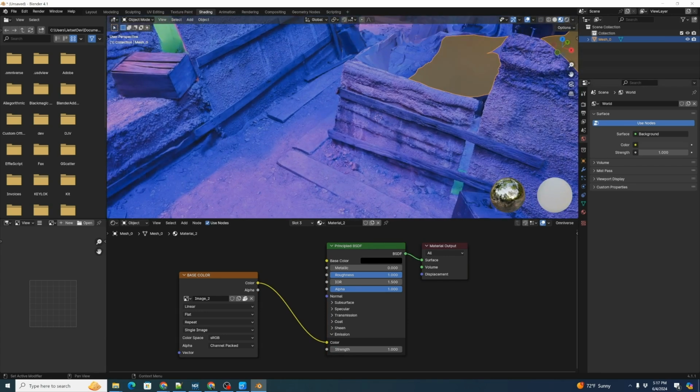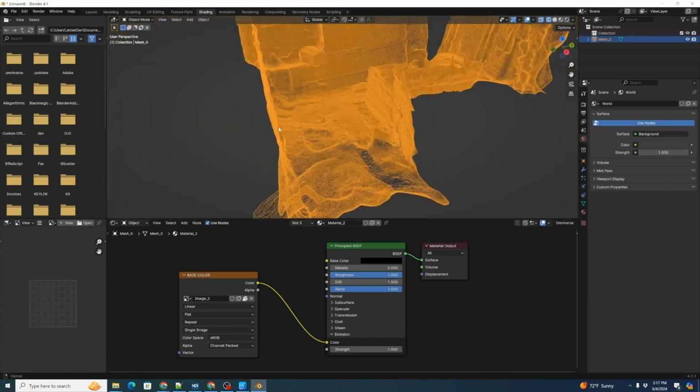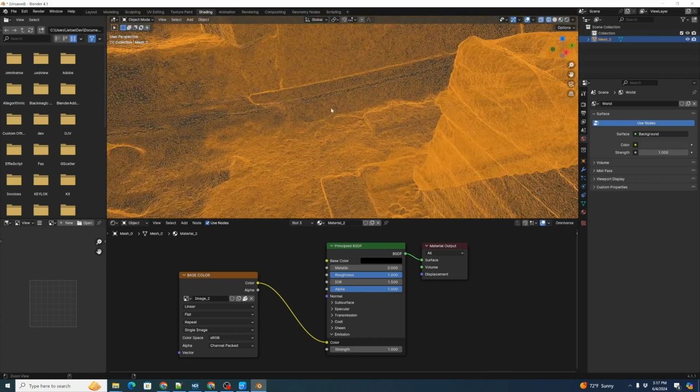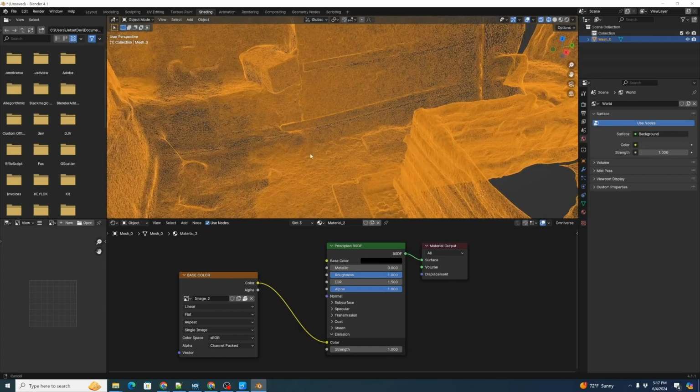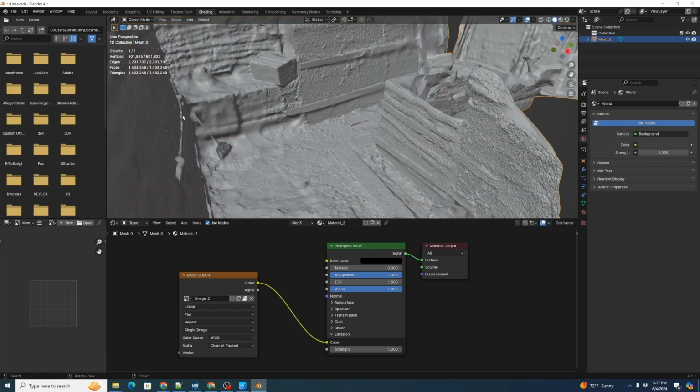The second thing we're going to want to do is take a look at this mesh. By default, that's a pretty heavy mesh. For the newer phone models, that can probably work, but I'm testing with an iPhone 12 Pro Max. That's a little bit older, and that's going to be a bit too much mesh for that. If we look at our statistics, I'm going to go over to here, and that is, wait for it, 1.4 million triangles. Okay, so that's a little bit much.